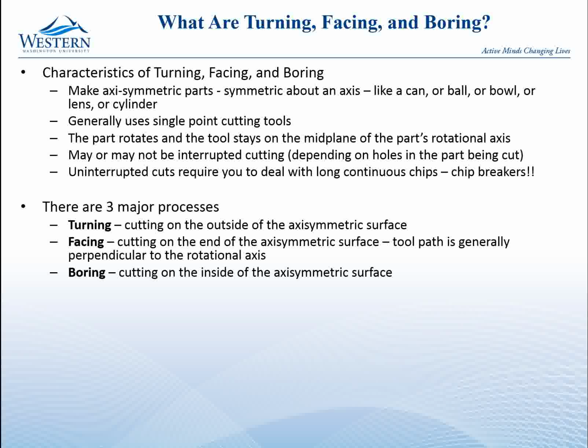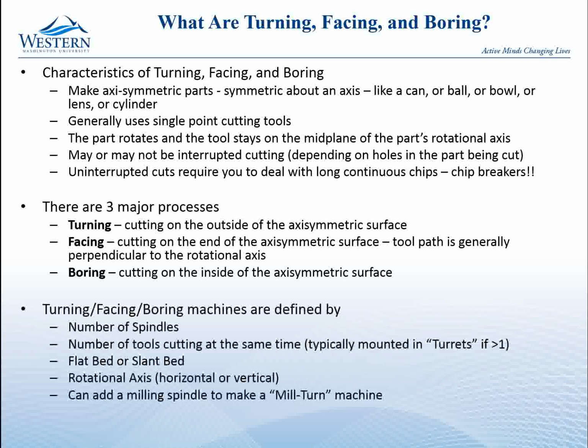The second is facing. That's where you're cutting across the perpendicular end plane of the material, and that's generally perpendicular to the rotational axis. And then the third one that we have is boring, and boring is like turning, except you're on the inside surface of the part. So if you had a hole down the middle and you were cutting inside the part instead of outside the part, that's the difference between turning and boring.